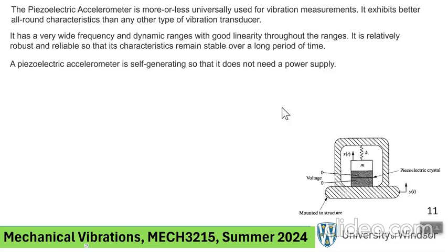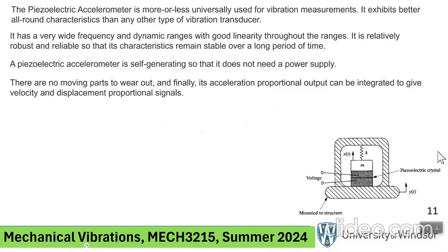That is not the case in the piezoelectric accelerometer. There are no moving parts. This mass, yes, you can think about it as moving, but it's pressing against this ceramic. And this is different from having literally main moving parts.